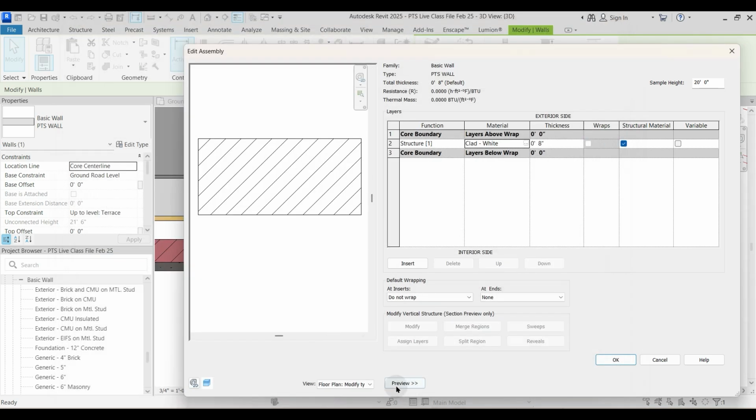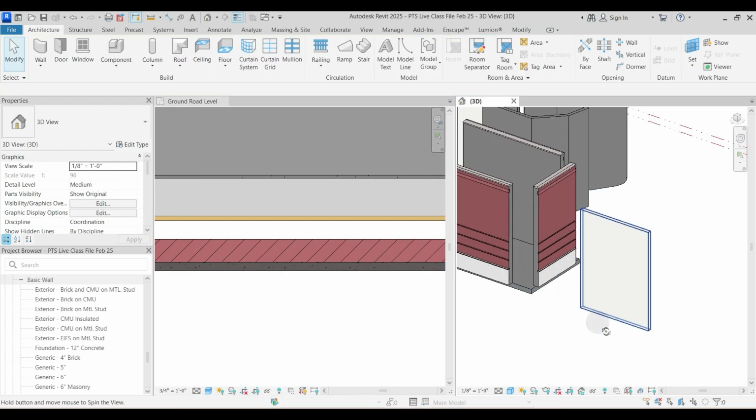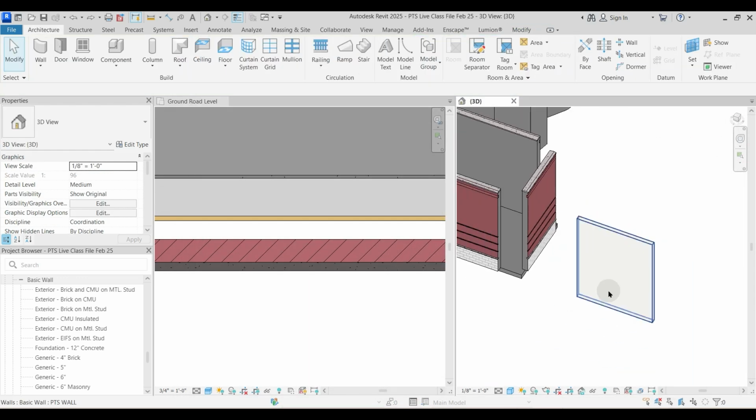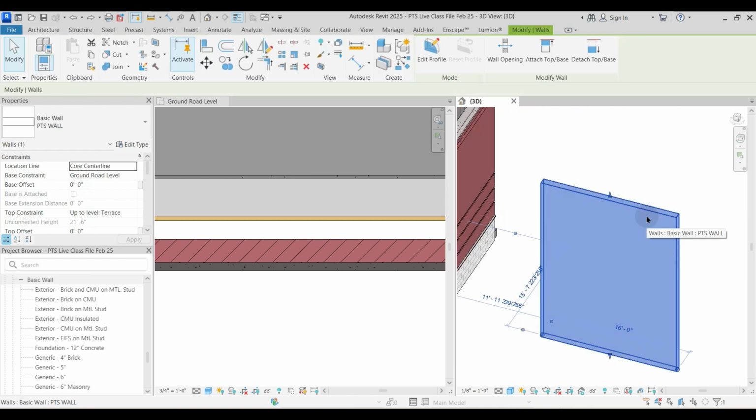And with this, you see that now in floor plan, this particular wall is getting cut. When cut, it is reflecting this particular pattern. Okay. Let me change this to 9 inch. Apply. Okay. Apply and okay. Fine. So undo. This was the wall, default wall. Redo, Control Y. We applied this material, and now visually this wall looks like this.